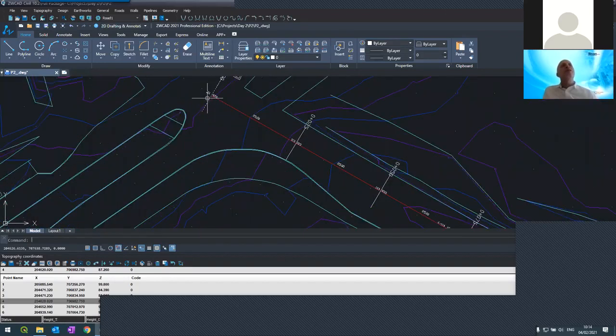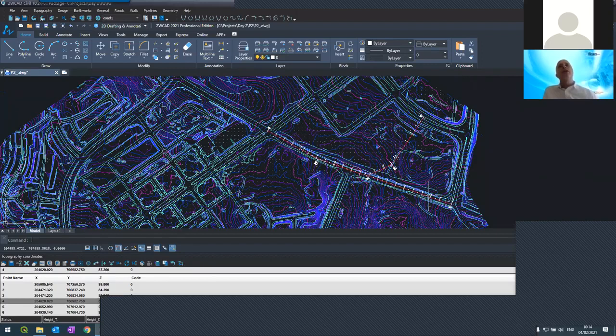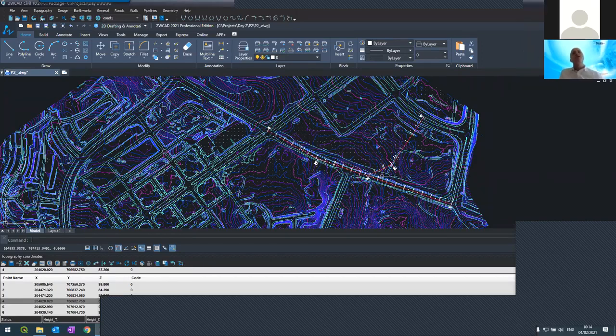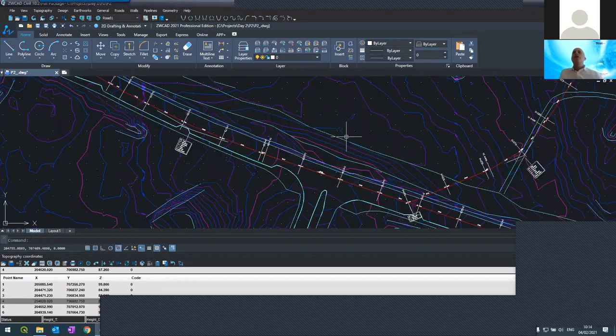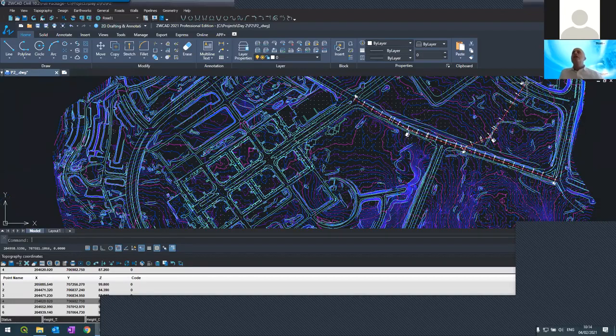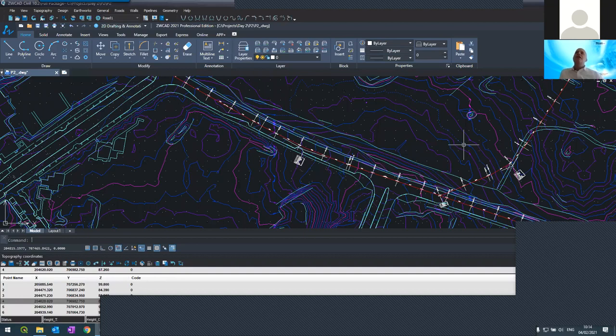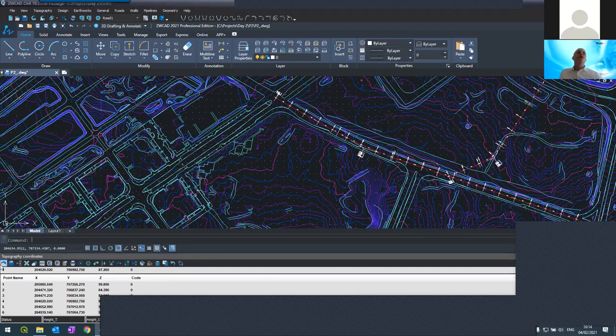So I started from the junction, went along, and used this tangent, this tangent, connected this curve here in the center, and then used the other road from here, the regular polyline. This is a new link between this existing road and this existing road. I hope this is clear, and I hope you're in the same position, because I want to continue my training from here.